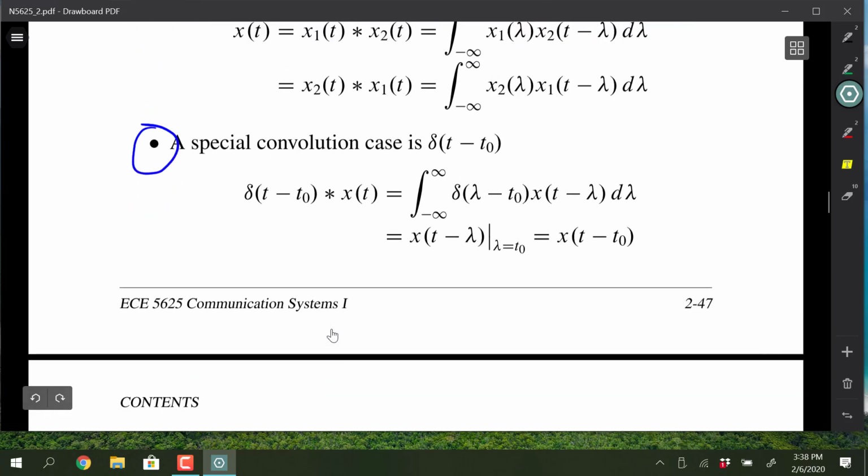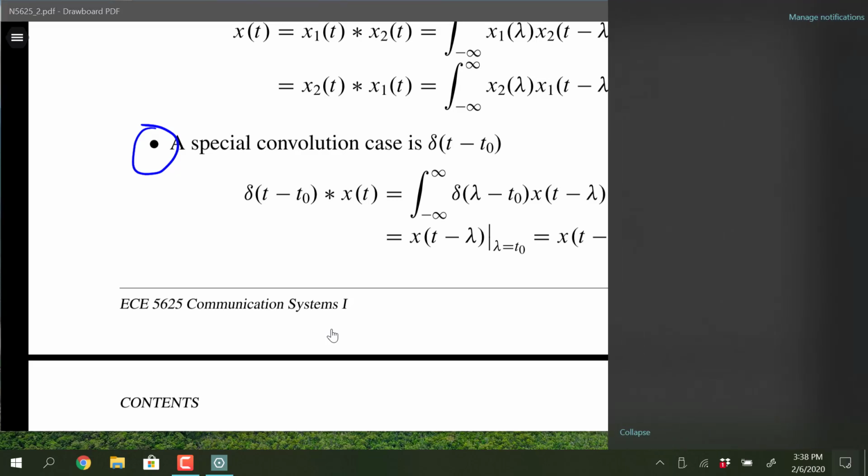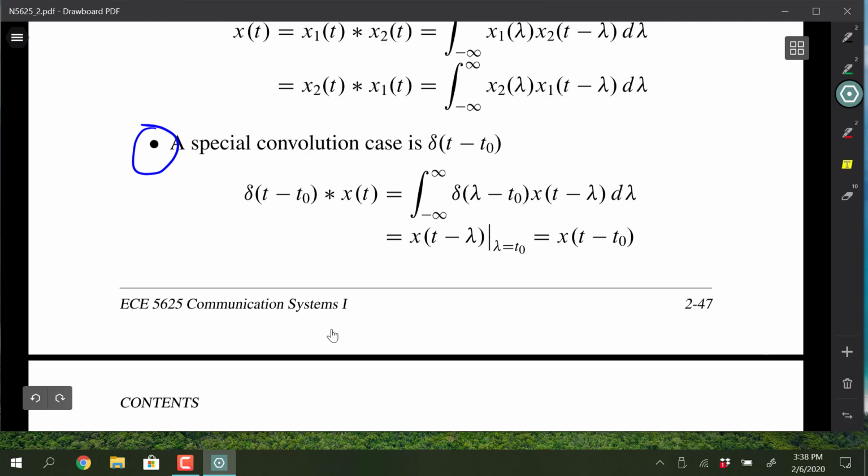The type of convolution, though, that you absolutely have to be able to accept wanting to do would be this type of convolution, where you're convolving a function with a delta that's time shifted in some way. That just uses the sifting property again, and you sift out the functional value of whatever is going on. You can rearrange these arguments if you want to.